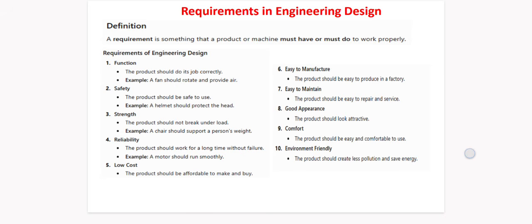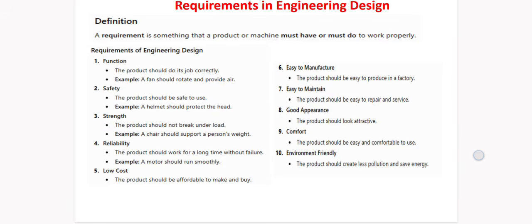Consider a simple design example for a ceiling fan. If we only specify design a fan, the requirement is incomplete. We need additional information such as required air delivery, fan diameter, rotational speed, motor power, voltage, noise level, weight, safety requirements, operating environment, expected life and cost.